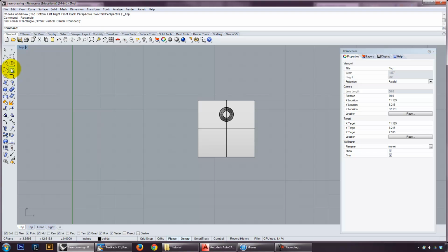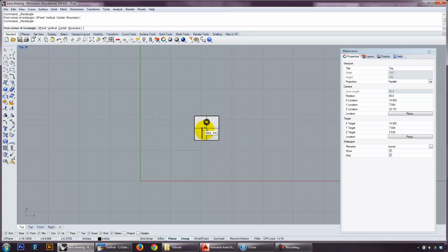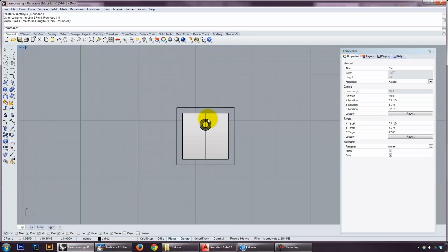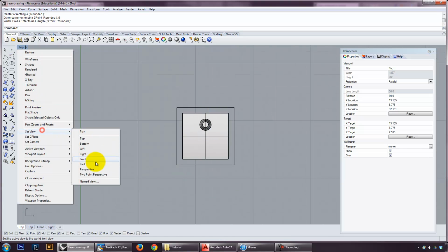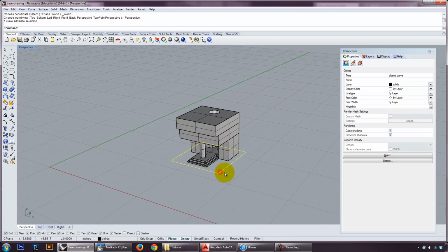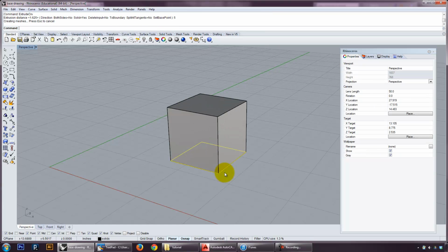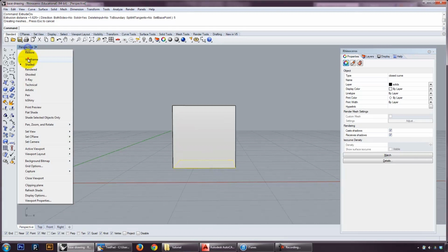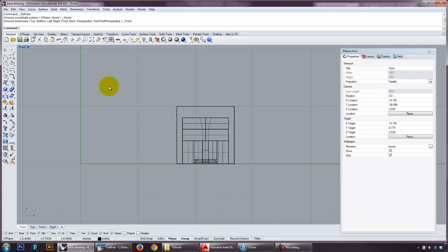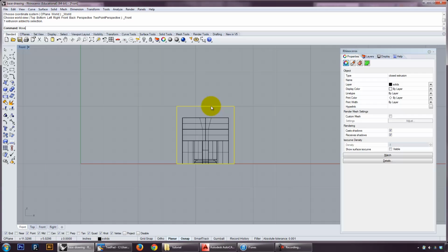So if I did, yeah, we'll do a center box. That's 5 inches by 5 inches. Okay, and we'll use this to be our box. So we're going to extrude it 5 inches. Let's look at it in wireframe here. Okay, front. Okay, then we're going to move it.